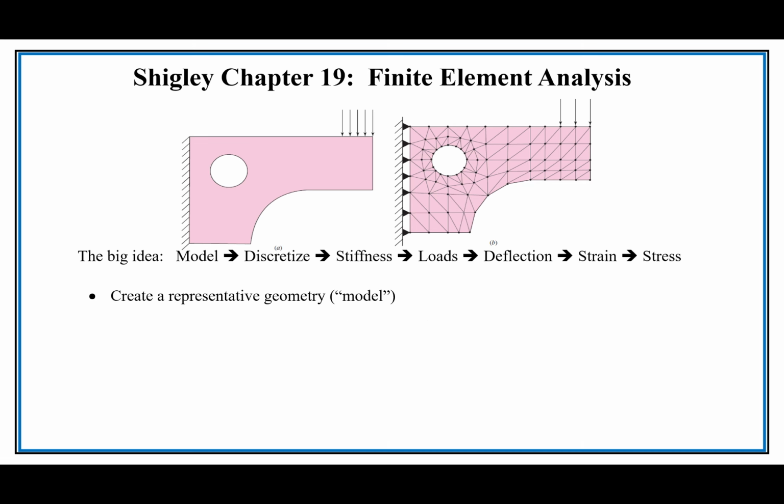So the model is generally considered the geometry of the thing that we're looking at, and the loading conditions, which include the forces we place on there, but also the boundary conditions. And those two things can play a big part in the quality of our results.